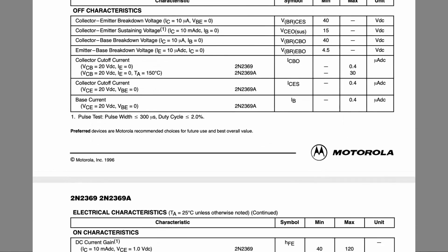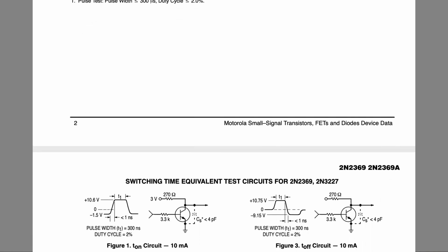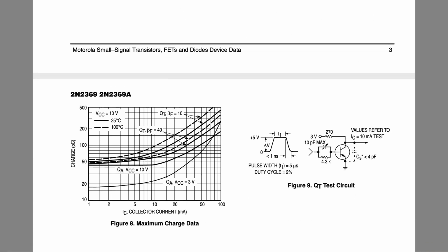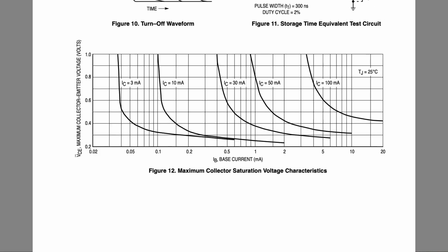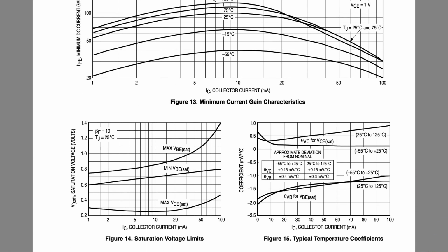They can be characterized by a lot of different parameters, starting by the type of junctions it's made of, to all sorts of nonlinear details like current flow through terminals, amplification parameters, and frequency responses. You just need to have a glance at a data sheet for a transistor to make it very clear that those are some seriously complicated components. The danger with using an equivalent table to pick a transistor that is close enough is that it may be close enough in many of those parameters, but not in the one that really counts for the circuit it's being used in.